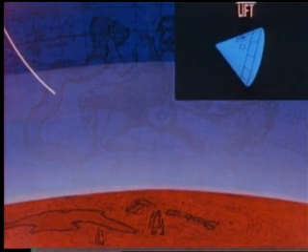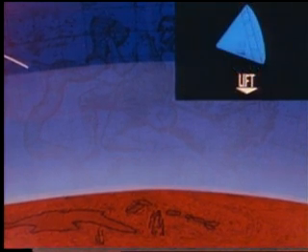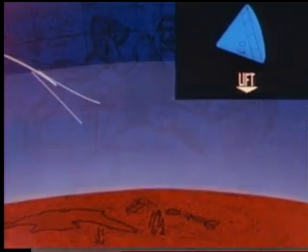If the entry angle is steep, a lift-up attitude can be held to bring the spacecraft onto a safe entry path. If the angle is shallow, lift-down can achieve a safe entry. Therefore, the entry range or entry corridor is expanded.